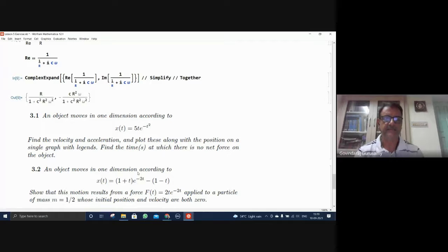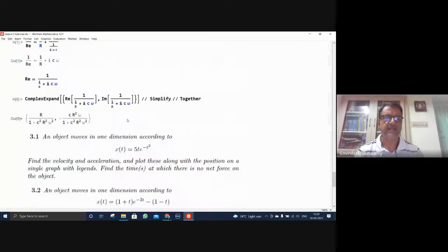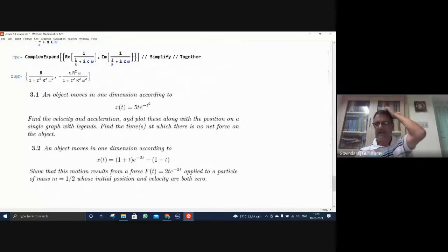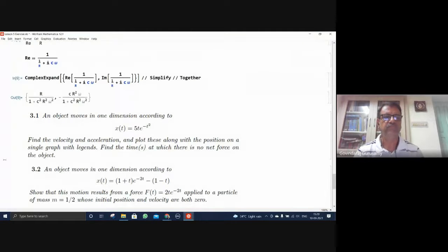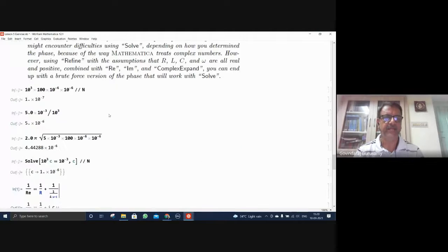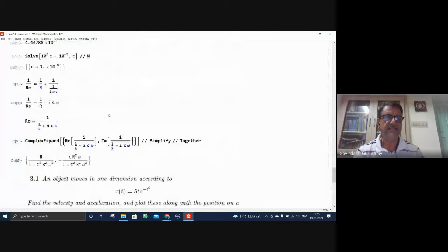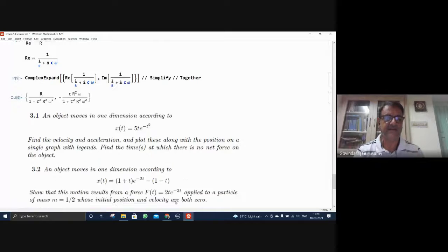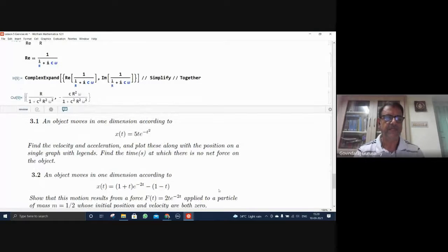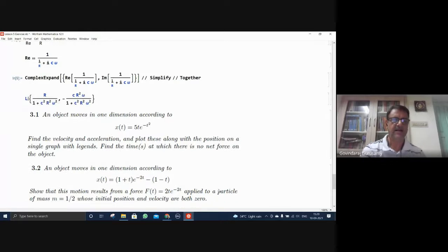I hope it's clear. Now, if I plot this impedance, that's what you ask him to plot. You can take an ABS value, or you can plot it independently, whatever you like, you can do it. But one thing is, you have to make a log linear plot. Then only it looks good, because you have to cover a wide range of frequency. Your time constant is how much now? 10 power minus 7 seconds. So your frequency should go beyond 10 power minus 7. I'm sorry, 10 power plus 7. Then only the spectrum will have the information. So what do I do now? I'll just take this log.